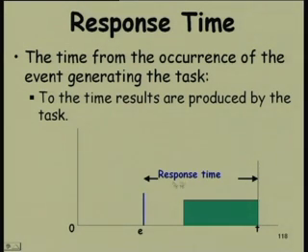So, the response time of an event or an action taken by the system, that is the response time. It is not proper to say that response time is with respect to a task. The proper way is to ask what is the response time of the event generated by the system in response to this. For this event, heater shut off, the response time is this. If the task generates some other events as it executes, possibly the response time of those events, right.